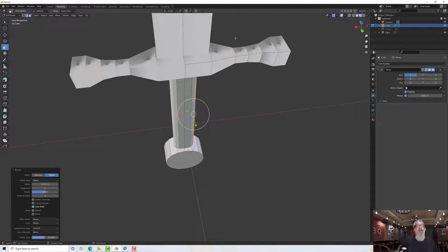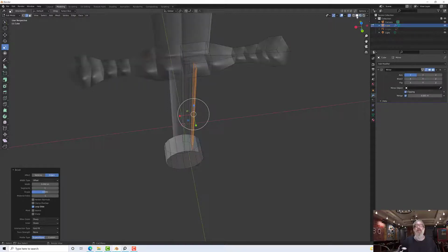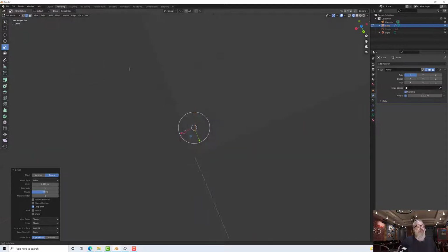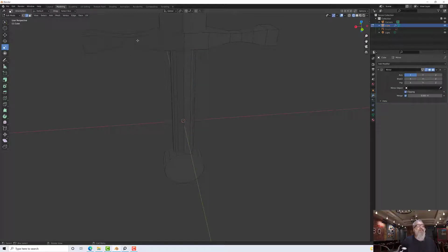So what I want to do, let's just go to mirror mode, transparency mode first, or if you prefer just wireframe, and I'm going to box select around these edges, if it'll let me. Oh, I'm on the wrong side of the mesh. See this dark side? You can't select it, that's your mirror. You have to do it on the slightly lighter side.